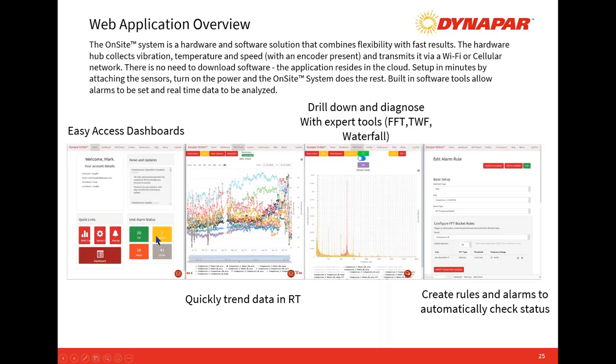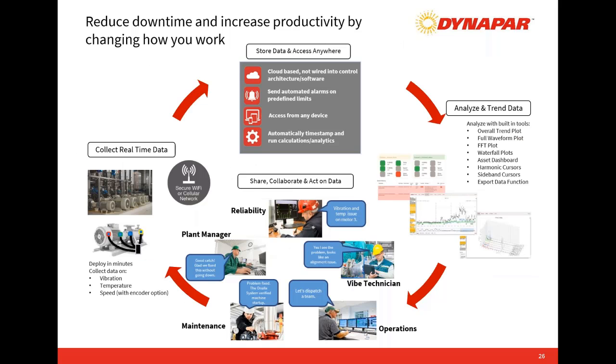So top level dashboards and trending, detailed time waveform and FFT analysis, and then really one of the main things here is a very customizable alarm panel for the vibration technician to be able to input what they know about equipment into the alarm panel such that it helps close the loop overall for everybody who has access and is tied into the system.